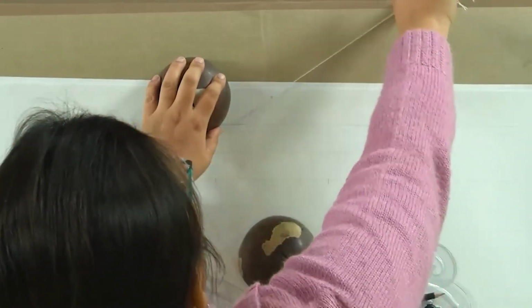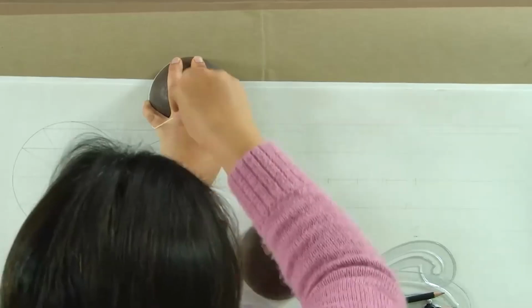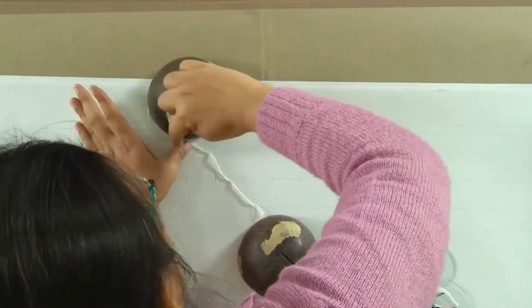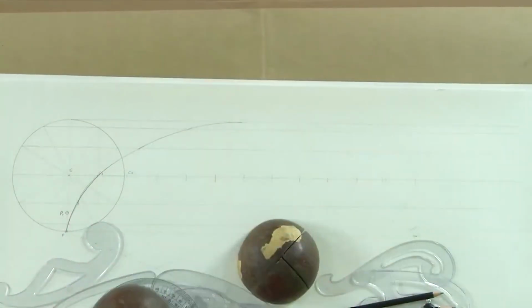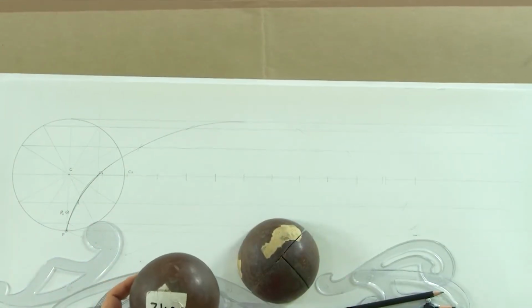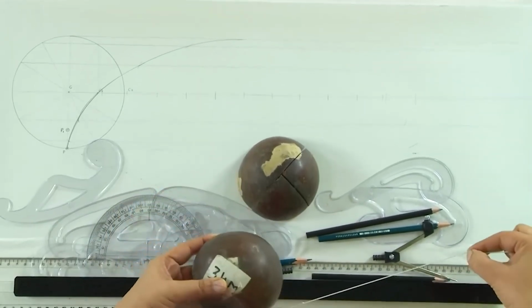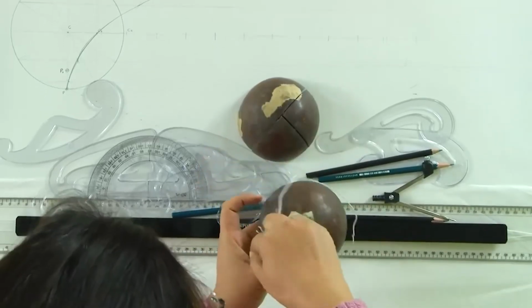If we keep moving this path here and the thread gets wound, and once it comes back, it is back to the original point, but the path that it has traced is the involute of this thread. The only thing that we have to assume here is that it remains in tension all the time, and the length of this thread is equal to the circumference or the perimeter. So, this is how the involute would be drawn.